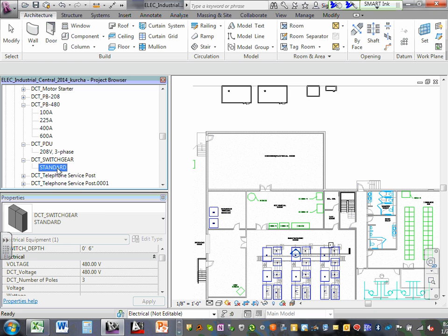They size them based on section. And the section that we size them are typically 30 inches, and Jerry's going to talk about 30 inch sections, and the depth will be 54 inches, and the height, I'm looking at the diagram here, 92. So imagine a box. Every section is 30 inches for the most part. Depth will be 54 deep, and the height is going to be close to 92 inches. Big sections. And each section can house no more than 4 circuit breakers.